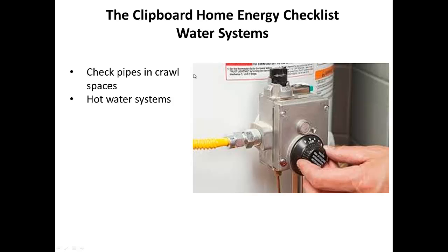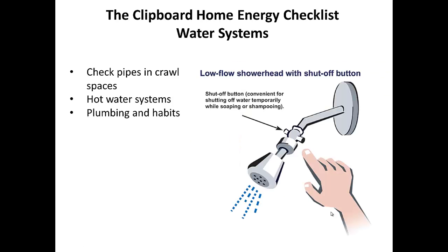There are insulation kits that you can put on the outside, but you want to be careful with those insulation kits, because if it's a gas hot water heater, you want to enable that gas to still be able to breathe, to still get air. So at the bottom down here where you light the pilot light, etc., you want to make sure that you've installed that correctly. And there are plenty of websites that show you how to do that.